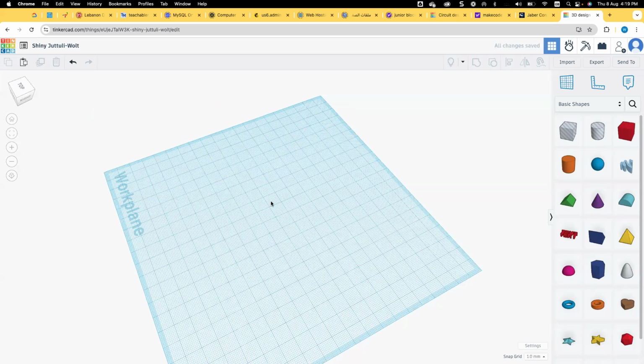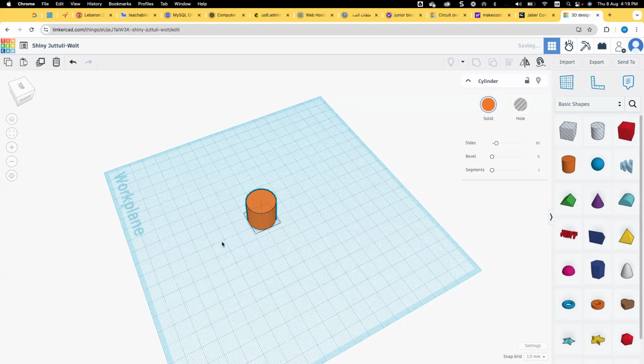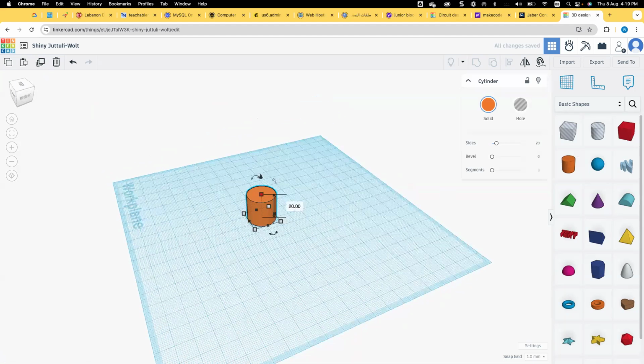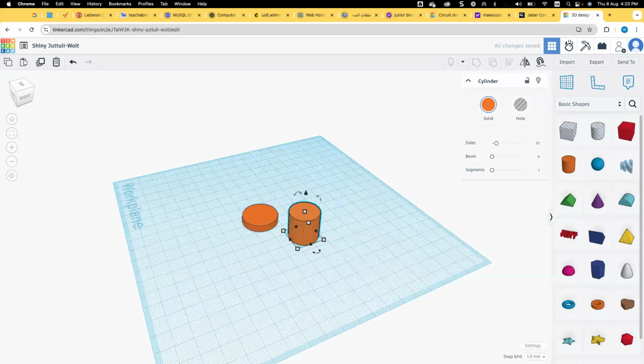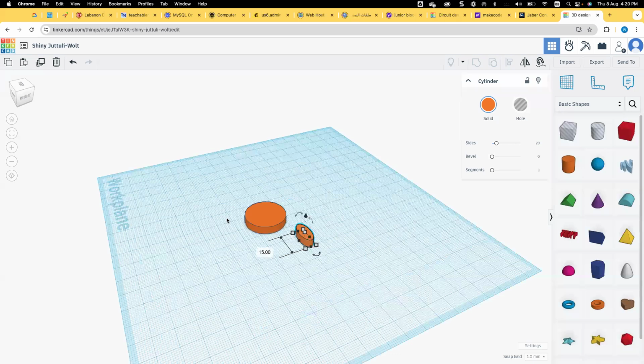Now let's move to another example, which will be more practical, which is how to create two gears synchronized on a base. So I'll start by creating a cylinder. I will make my height 5 millimeters, and the dimension is like 25 by 25. Then I create another cylinder of 5 millimeters, and I change the dimension manually in order to make it like one of the gear teeth that will be duplicated on the cylinder. So I assume that this is it.